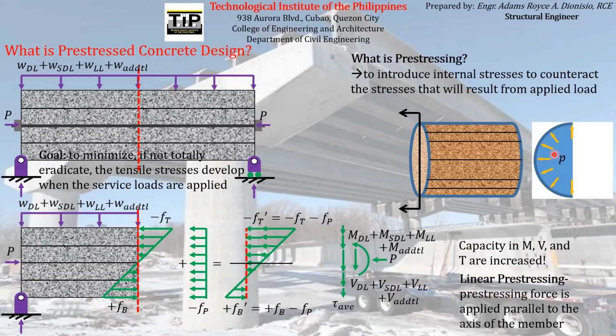If you can remember this topic, it is similar to the topic in mechanics of deformable bodies or fluid mechanics, the circumferential stress or the tangential or longitudinal stress. This is the same in those topics. So the effect of the water contained inside the barrel is that it pushes away the wall of the tank or the barrel, the wooden stave.